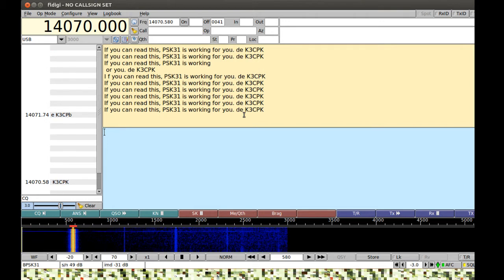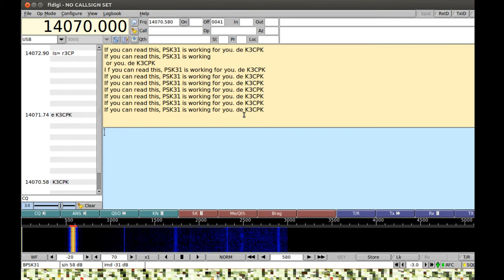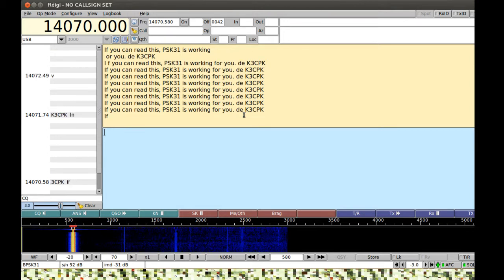What really concerns me is the way your waterfall looks. It just looks wrong. I feel like it shouldn't look like that at all. And even over here, you come in the background. Well, okay, that's because you got your dB settings changed, but that shouldn't affect how your signal in FLDigi looks. If you've got enough time to beat your head against it one night, go through and try to make your waterfall look like how mine does up on the projector screen, or try to find someone around here that has one that looks good.